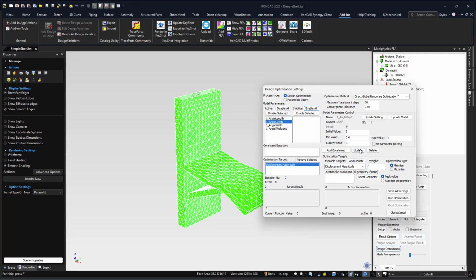The depth inside of here, again, we can set the minimum. We'll say maybe 1.5, and the maximum on that value, this whole total distance was 5 something in there. So we'll set that to about 5 as well. So we'll set those two main drivers for that. And then our width, again, the maximum width of this thing can be 5. And maybe our initial value, we'll set it to 2, and the minimum, let's just say the minimum is 1 for that. So we're just going to set some ranges that we want for our design.